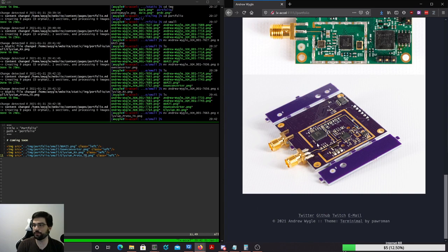Okay, so this is the prototype of that Elysium radio. This is the transmit side. That you can see there, that's a Class C power amplifier, and it basically can achieve 50% efficiency as long as you have a constant peak to average power ratio. So it works really well for frequency modulation, like frequency shift keying, but it's not good for certain kinds of phase shift, and certainly amplitude shift keying would be terrible on that. It adds a lot of distortion to the more analog modes of transmission, but for something that's just simple frequency shift, it's perfectly functional, and it's very efficient.